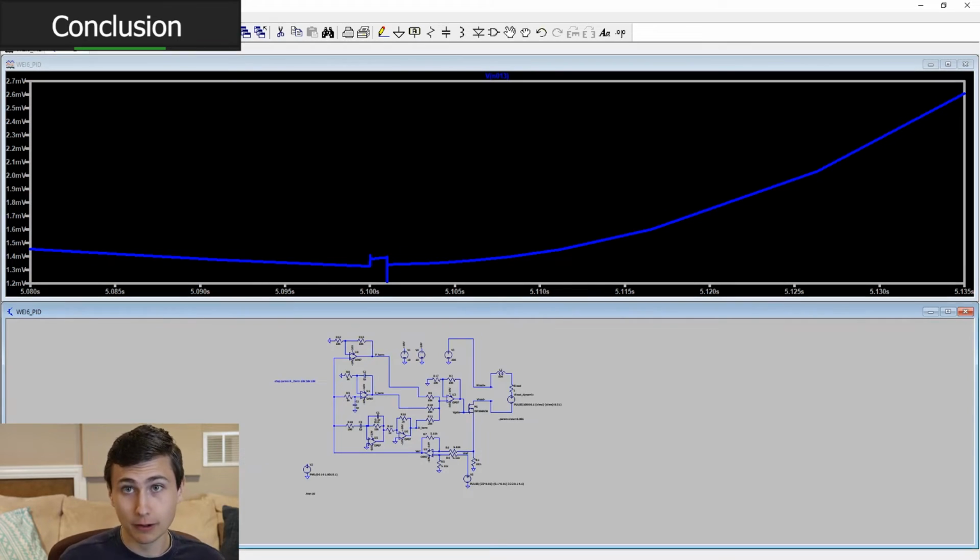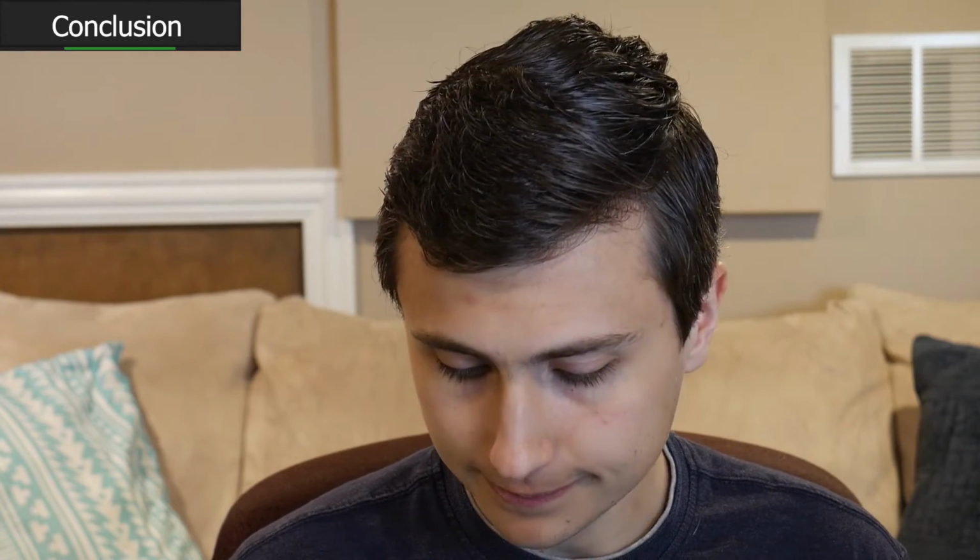Now, this might look very promising. If we even threw a linear MOSFET instead of a switching MOSFET, this could work pretty darn well. I really love this controller. Basically, we just have a PID controller connected to an error amplifier that happens to be monitoring a programmable threshold. Perhaps that's coming from a DAC, perhaps from a voltage source, perhaps from a resistor divider. But wherever that reference voltage is coming from, it's being compared to a current shunt, and that is coming into this controller and ultimately driving a MOSFET.